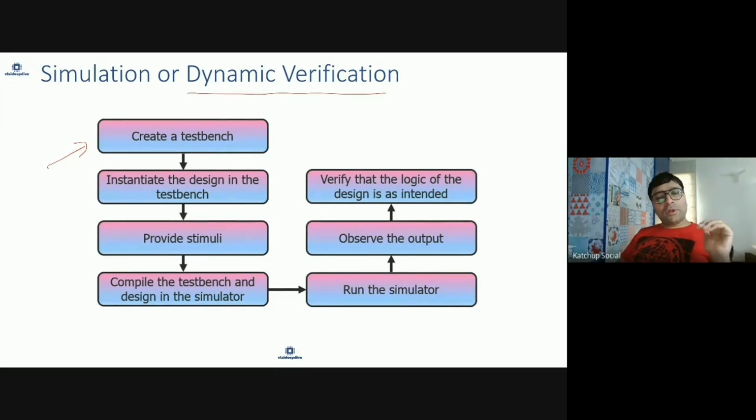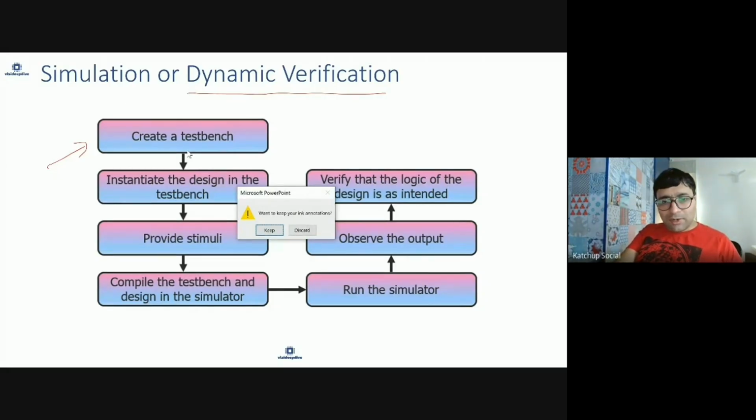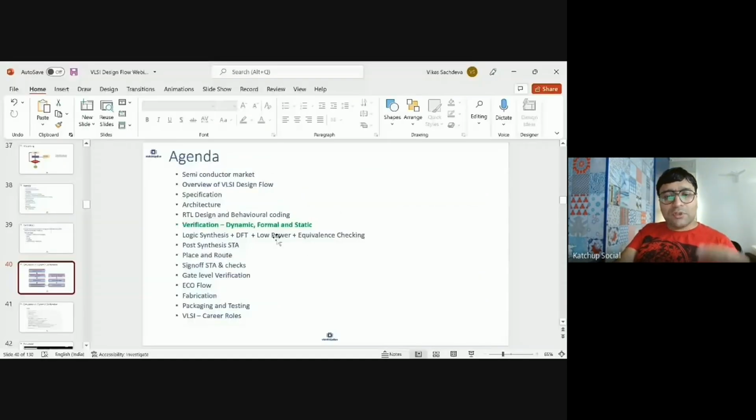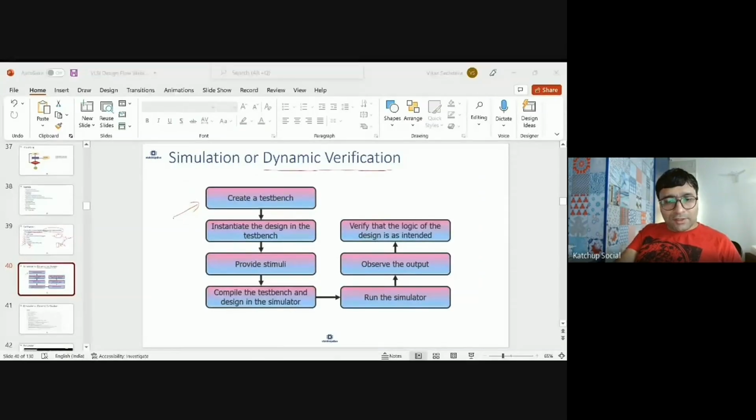For the counter, you will initialize something, then give some input signals, then observe the output signal. What input signals will be given and what the expected value of the output should be are all coded in Verilog itself in your test bench, or it can be VHDL. The test bench puts your device under test and verifies what you have implemented.